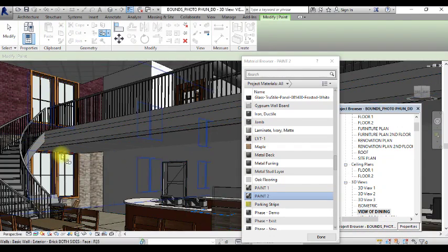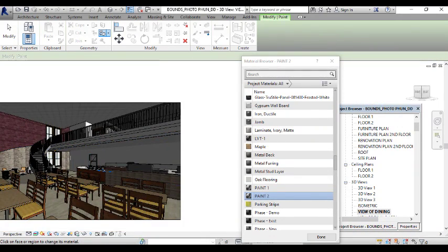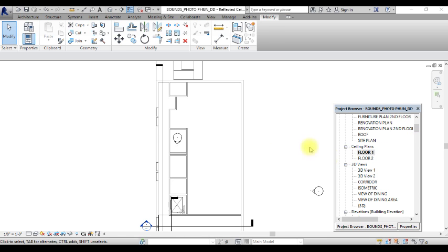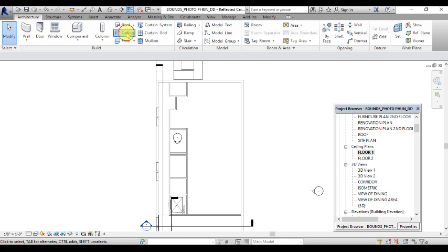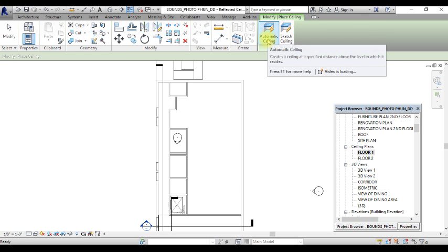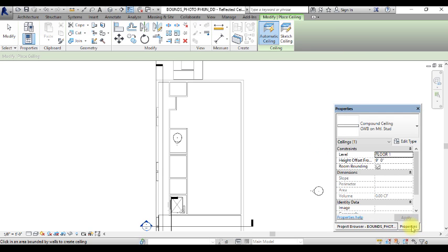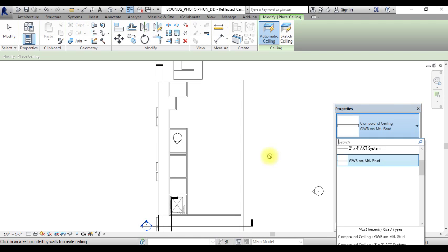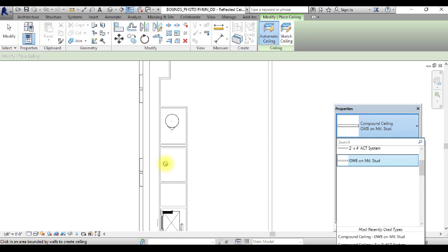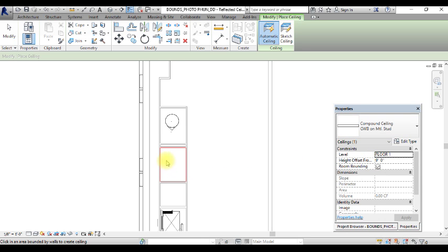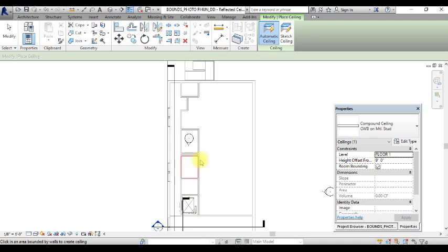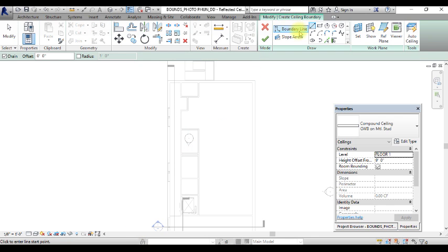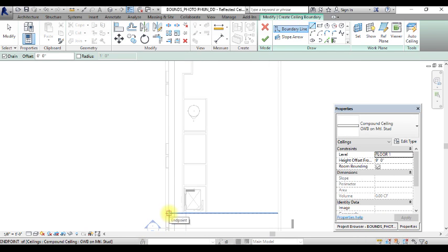So Revit gives you the ability to explore design options and different materials pretty quickly and get your ideas sort of figured out in 3D. So I want you to be able to put in ceilings in all of your spaces. The kitchen will need a ceiling. We'll show that in a later thing, but I'm going to put the restroom ceiling in, and a ceiling. I'm going to begin an interesting ceiling at the hallway as well. So I just put a chipboard ceiling in those 2. I used the automatic ceiling, and now I'm going to do a custom ceiling at the hallway.